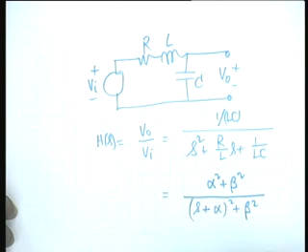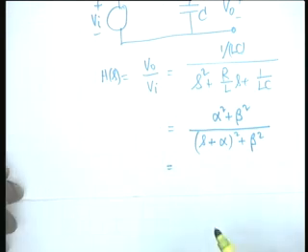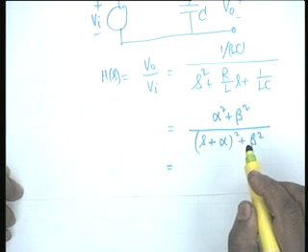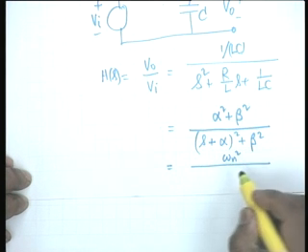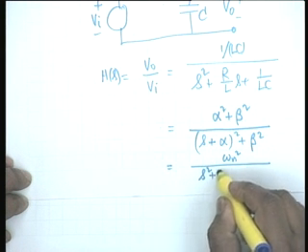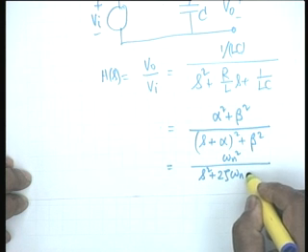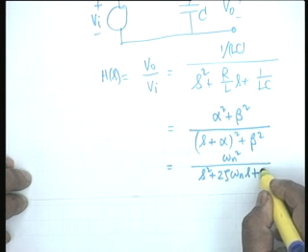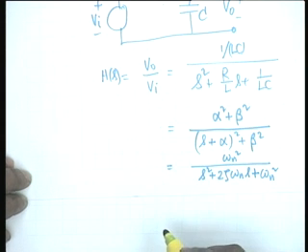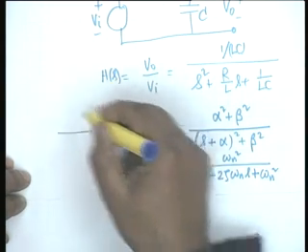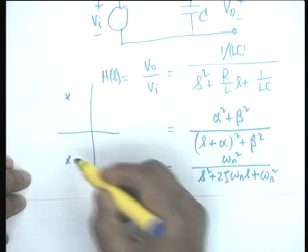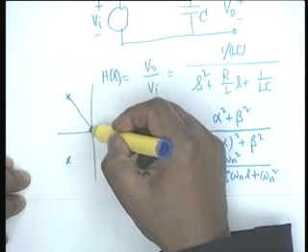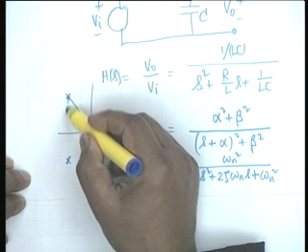We also put it in a slightly different form in terms of omega n and zeta, and we showed that this is omega n squared divided by s squared plus twice zeta omega n s plus omega n squared, where zeta is defined as the cosine of the angle theta.